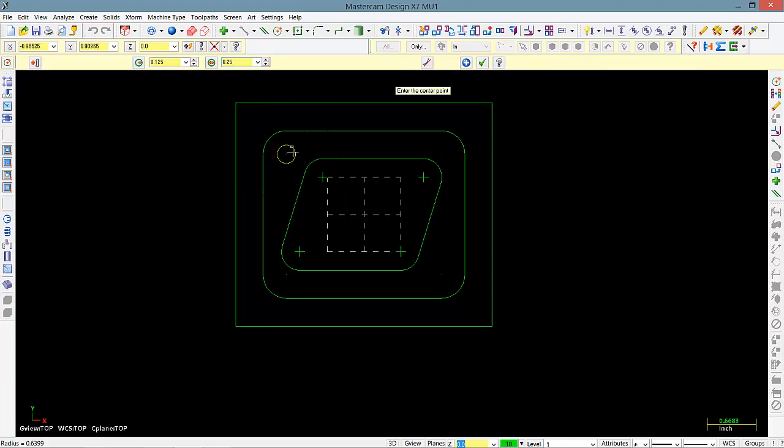So I want to make another circle that's a 1/4 inch, right? I'm going to lock this down. So if I click the diameter button or the radius button, doesn't matter, it turns red. Red means that value is locked, and I can make as many of those circles as I want. So I'm done with this one. I'm going to hit apply.